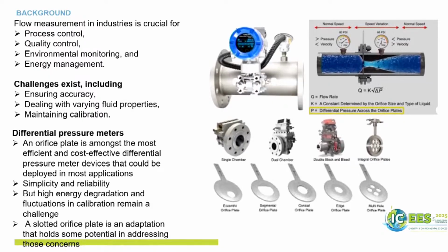As you can see on the sketch, the charts show the way they are installed and the governing theories that guide their operation. Normally they are installed on flanges, and we have differential pressure meter tappings upstream and downstream. The distances of those from the flanges where the plate is installed are governed by the ISO standard.